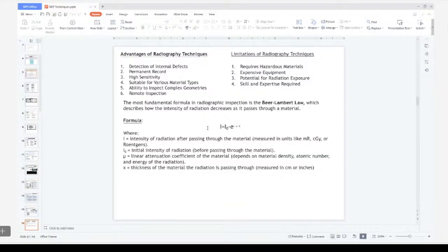The immersion technique is used for certain materials. When the sound wave travels from one medium to another medium, there is a thing called impedance. When the difference in the impedance is very high, the intensity of the sound waves getting into the material will be significantly reduced.